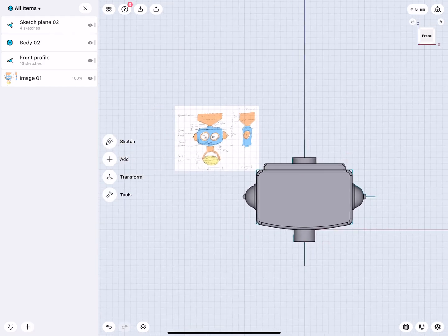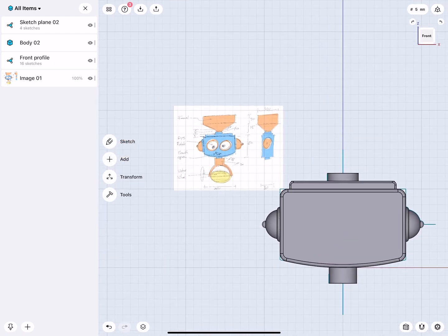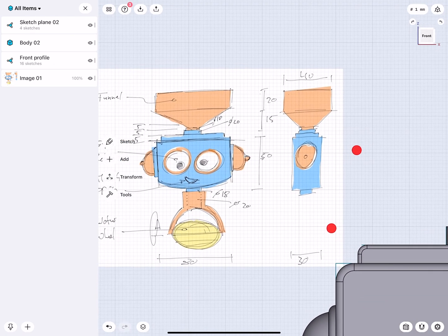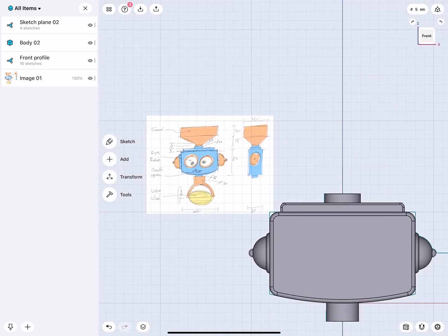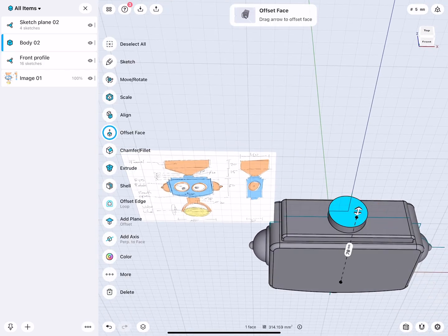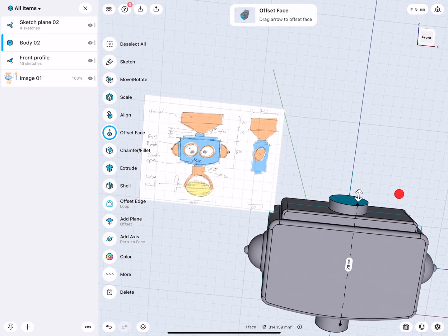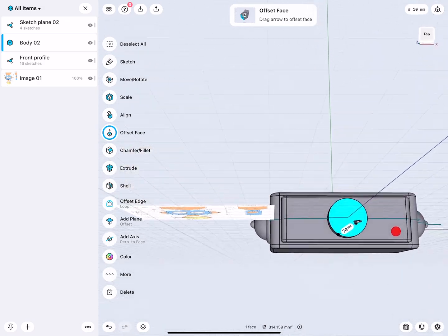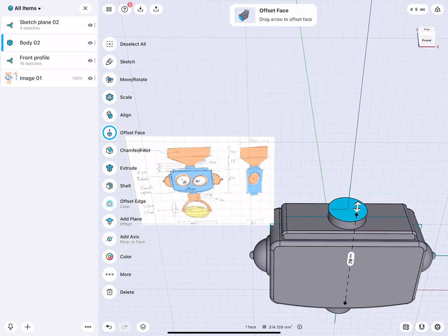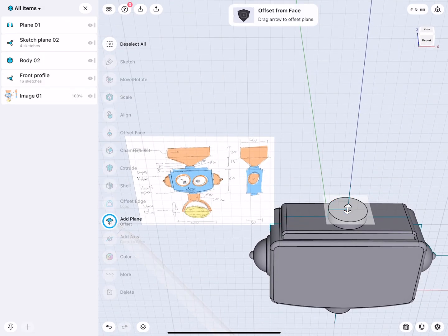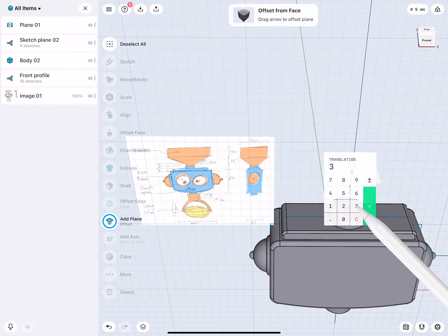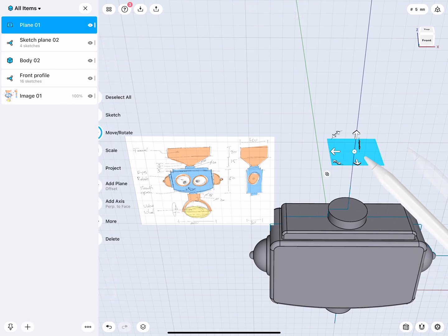Brilliant. So we have to do the funnel. 15 from the socket up, and 20 is then the big part. From here I need to draw somewhere an ellipse, but I don't have there something to draw on. So I select this top face, go to offset plane, 15 and 20 makes 35mm. There we are. There's my new construction plane.